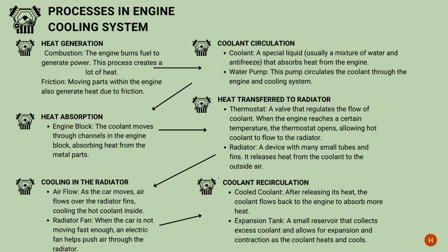So the fifth one is cooling in the radiator, which consists of airflow and the radiator fan. Airflow: as the car moves, air flows over the radiator fins, cooling the hot coolant inside. And the radiator fan: when the car is not moving fast enough, an electric fan helps push air through the radiator. And the last one is coolant recirculation.